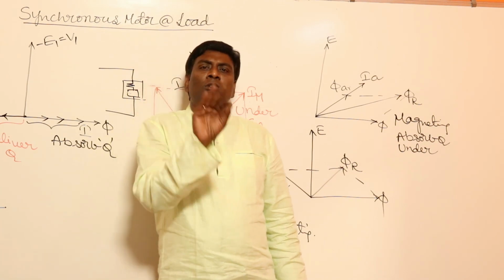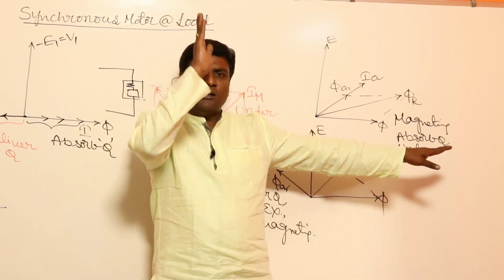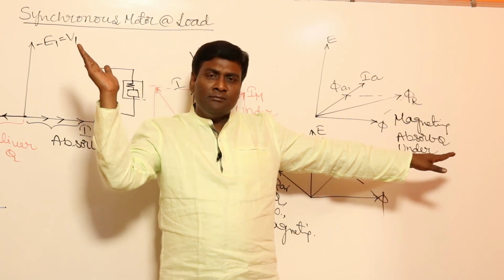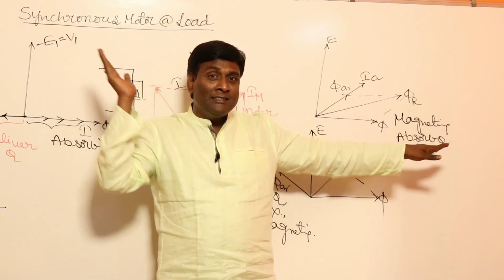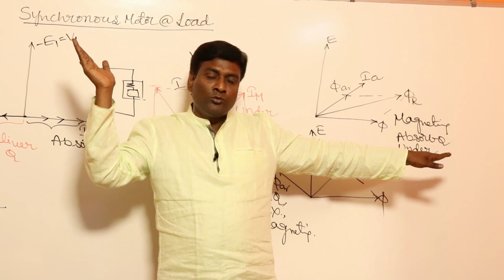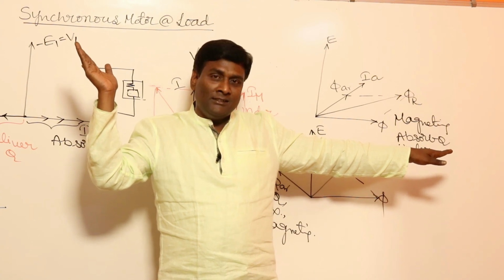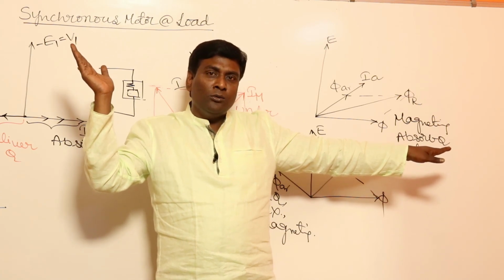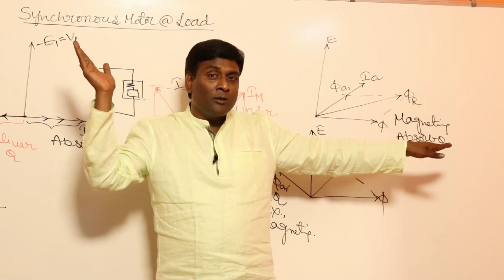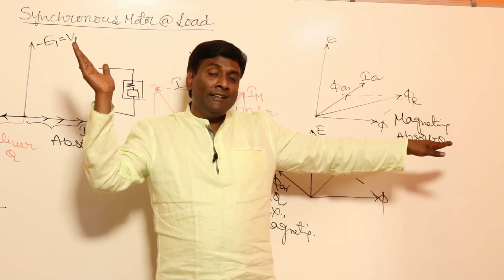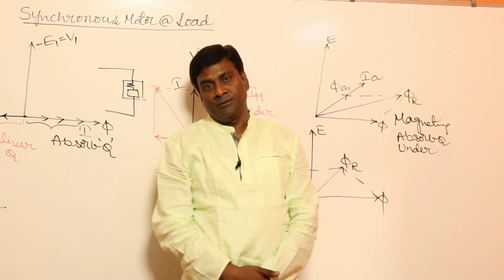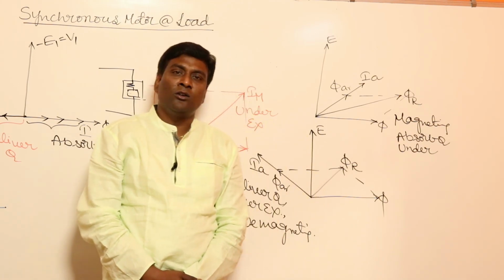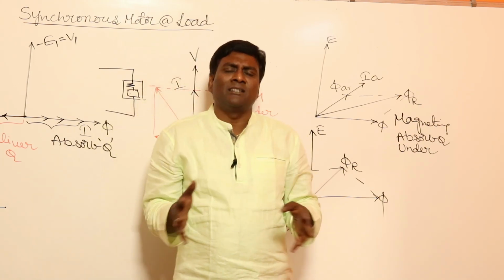So altogether let us combine: a motor operating at leading has demagnetizing armature reaction effects, so it should be overexcited. Now, it is having demagnetizing armature reaction effects. A leading motor supplies reactive power. Now, let us think of a motor, don't remember this.